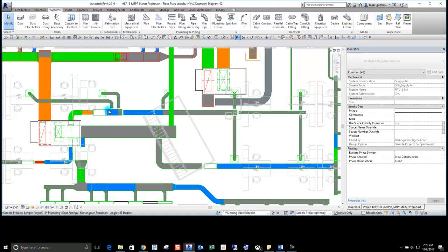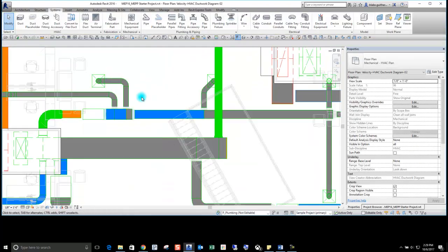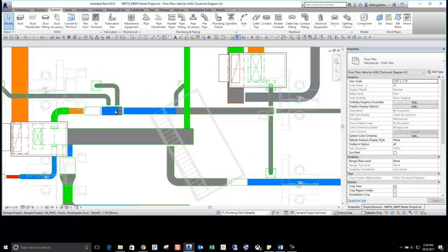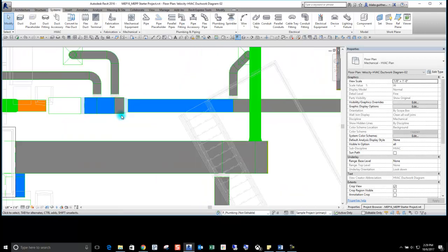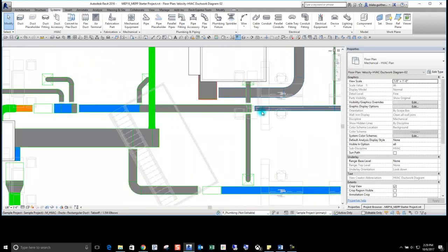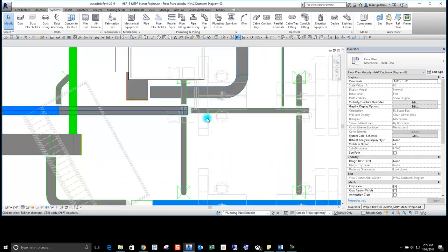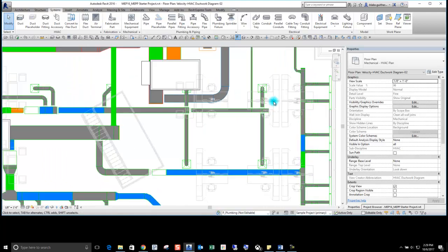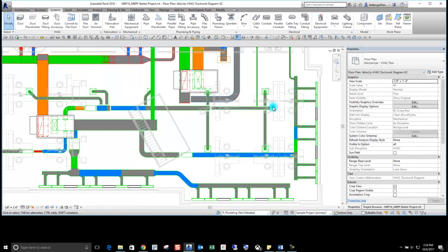And there we go. We've used Revit now to size the branches and the duct mains. As you can see, a reduction here was made in duct size, and then also here where I put those unions. And so you can update these sizes now as you need. Now that you have connected airflow, you can actually use it, which is a huge benefit.